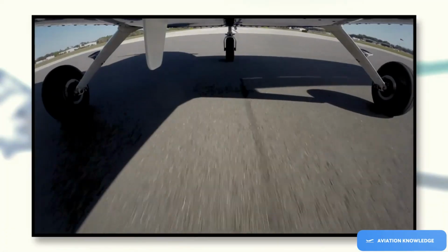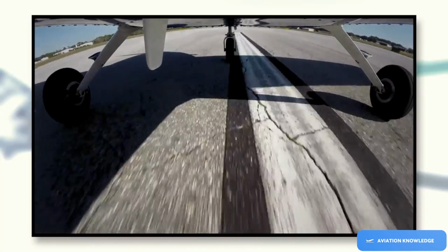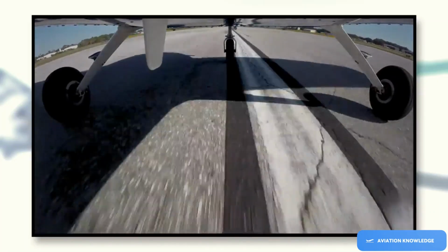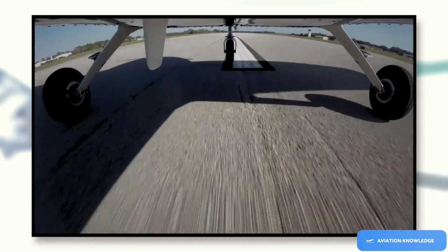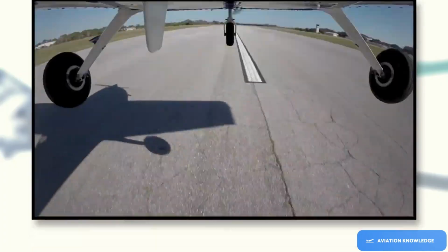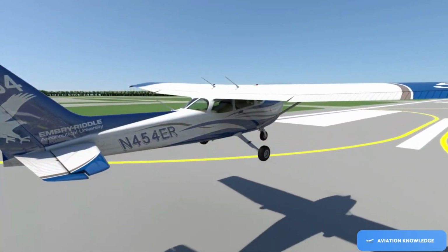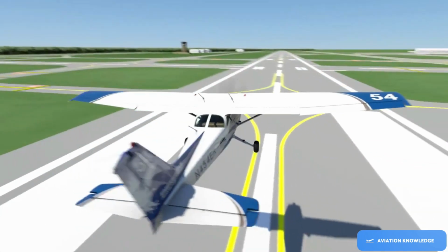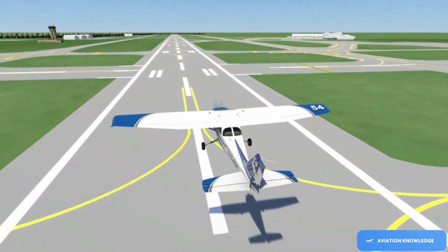As the airplane lifts off the ground, the downwind wing and wheel should rise and lift off the runway first. If gusty winds exist, the rotation may be slightly delayed in order to allow the airspeed to rise, allowing a definite takeoff without settling back onto the runway. Once the airplane is in the air, it should remain on the extended runway centerline just like a normal takeoff.